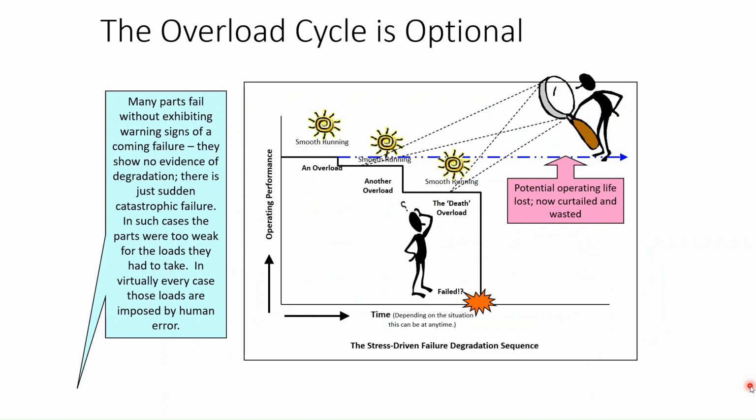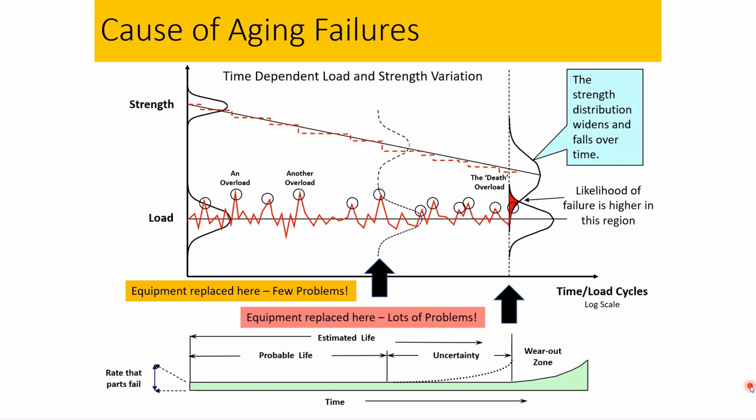Wear-out failures are any failure mechanism that results from parts weakening with age and degrading usage. Included are processes involving material fatigue, wearing between surfaces/substances in contact, corrosion, degrading insulation, and wear-out in light bulbs and fluorescent tubes. Initially, the strength is adequate for the applied load, but over time the strength decreases. In every case, the average strength value falls, and the spread of strength distribution widens. This makes it very difficult to provide accurate predictions of operating life for such items.